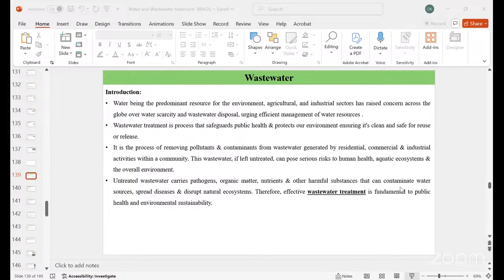As we see here, the sludge is generated, and there is a sedimentation basin where a huge amount of wastewater is allowed to settle in order to settle the suspended solids. Coming to the key considerations of the sedimentation process, it is important to understand the different types of sedimentation for designing and operating effectiveness in water and wastewater treatment systems. The type of sedimentation that occurs depends upon the characteristics of the suspended solids and the concentration of the suspension. It is also important for understanding real world applications. Sometimes the sedimentation process will exhibit the characteristics of more than one of the listed types.